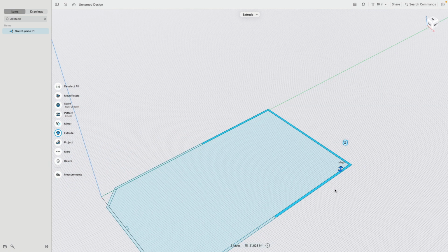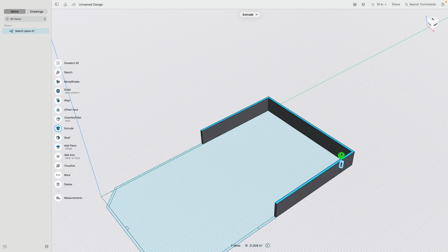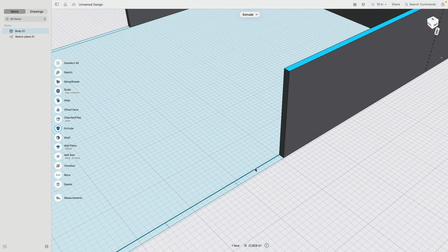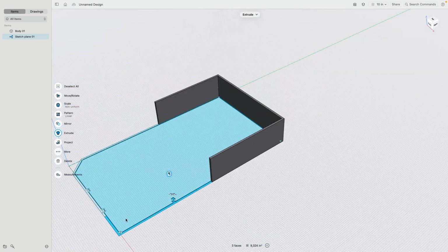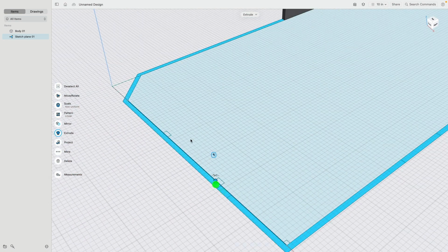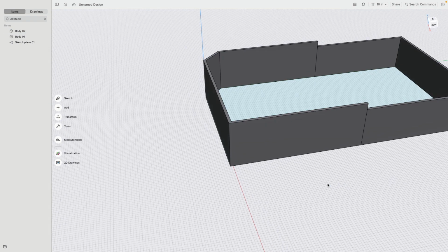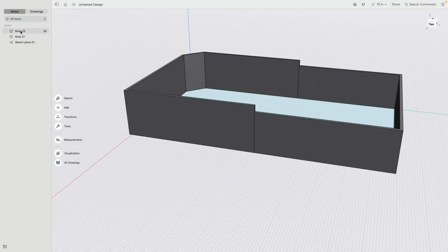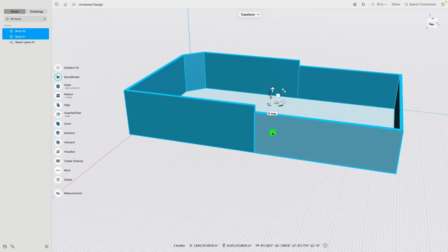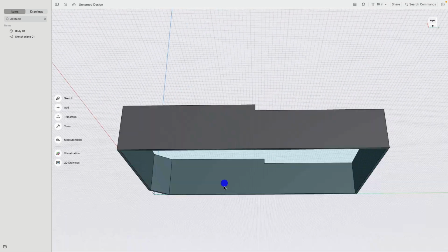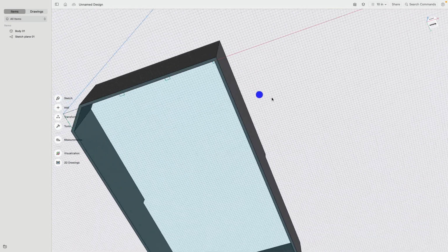So you see with Shift and mouse button, I clicked on the individual profile elements and then I extrude the wall up by 191 inches. Then I will select the missing profiles, and this we extrude up 221 inches. Very good. We now have two bodies. Double click, shift, double click, union. We fuse those together. Beautiful. Okay, you see that was pretty easy.